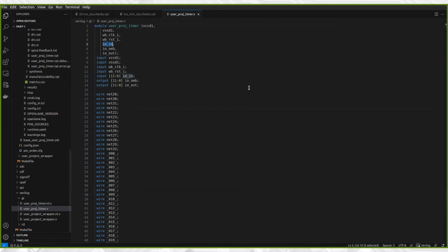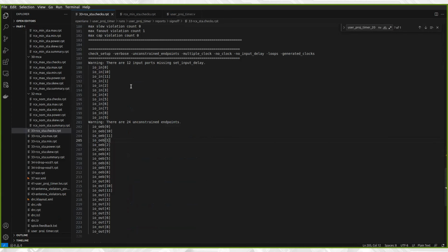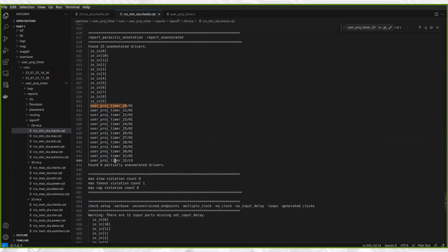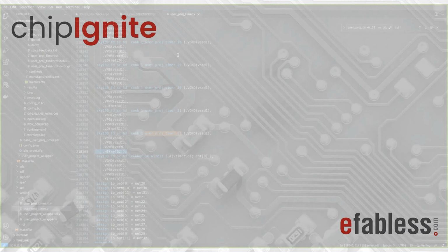The reported nets are in the IO_in star pins that are not used in the design and are unconnected, so they don't have any parasitics. Additionally, reported nets are the unconnected constant output from the Sky130 CON-B1 standard cells. Therefore, all the unannotated nets are fine. We have verified that the input SDC is not missing any constraints and the parasitics annotation has been done successfully.